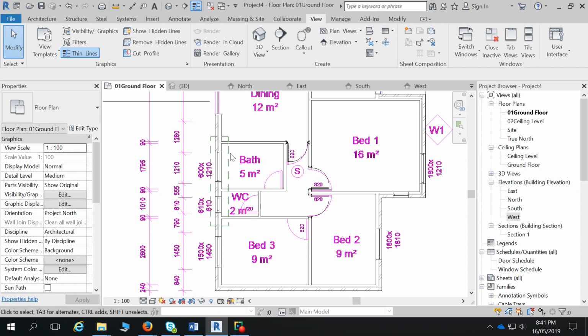So that's quite an important tool to know is there, because the project will probably start next week. Has the same scenario come up where the toilet window is small, and once you put it up to the correct head height, it disappears off the floor plan? Funnily enough, if I had tag on placement on, the tag would still be there, but you wouldn't be able to see the window. You check the elevation, but you can't see it on the floor plan.